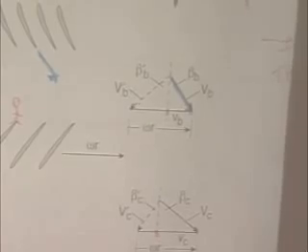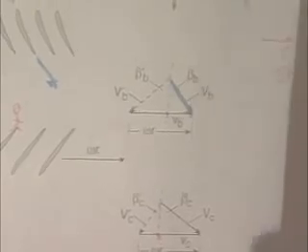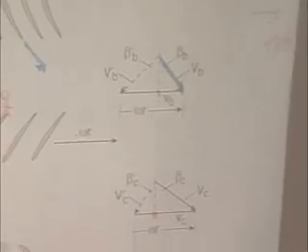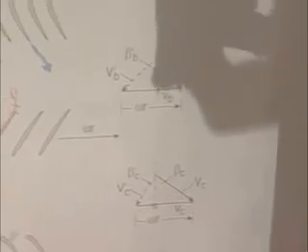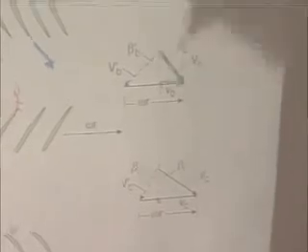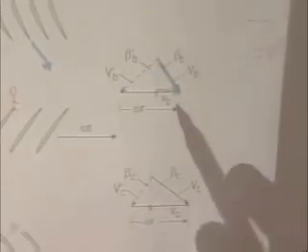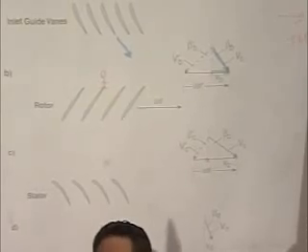So you've just solved part of the problem. You just found the tangential component of the velocity in the stationary reference frame coming into the rotor. It's this little green arrow right here. Can people see that okay? That's sort of the easy part. You haven't gotten to a moving blade row yet.